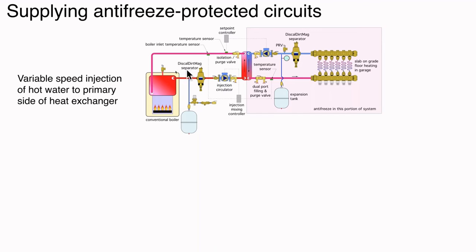Over on the left, this is water, okay? And again, it's a closed, isolated circuit. It has the same trim details. It does, in this case, have an automatic makeup water system on it. Now, this is actually using a variable speed circulator. We have some type of controller. It might be built into the circulator.